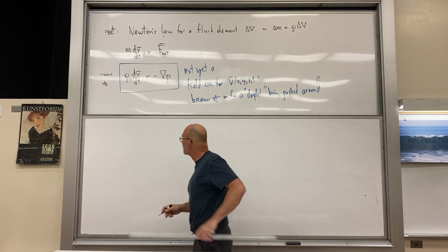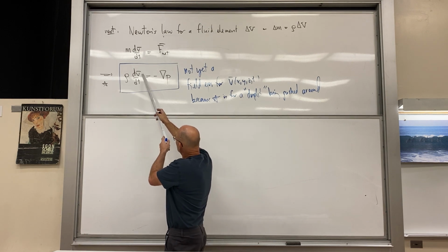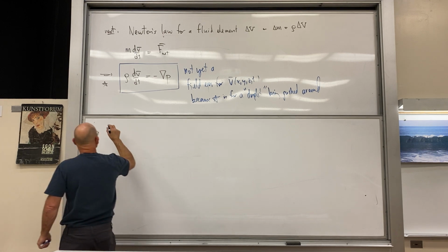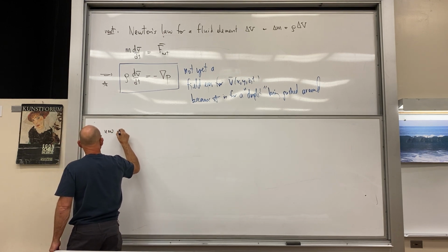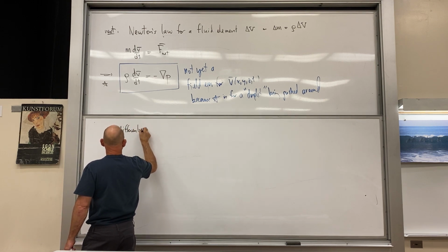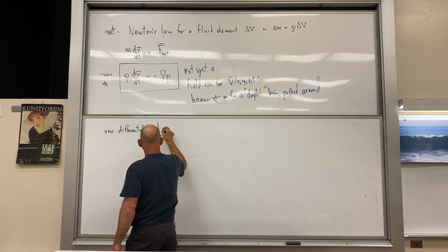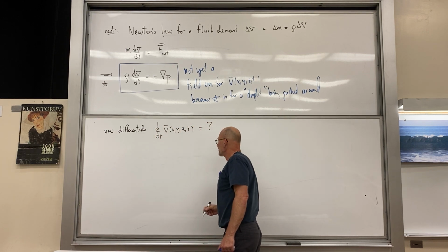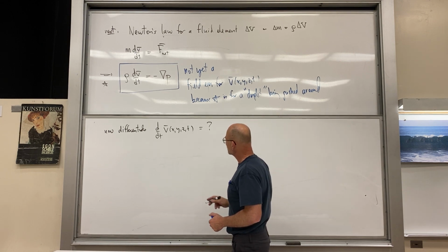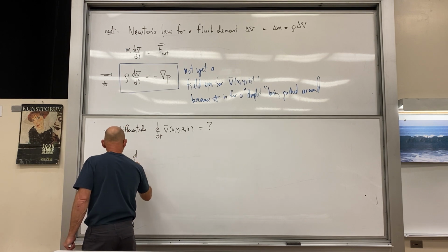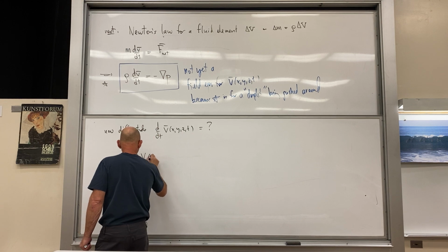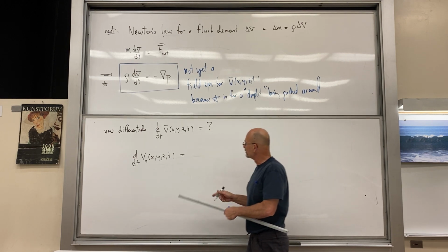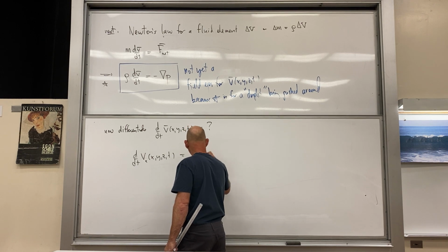What we're going to do is treat this velocity of the droplet as this thing, and just take its derivative and apply a little chain rule. So now differentiate d dt of v of x, y, z, and t. And we'll just do the chain rule on it. In fact, let's just do it for one component. Time derivative of v sub x, of x, y, z, and t. And we'll go ahead and take the explicit partial first. So there we have dvx dt, and then we'll have